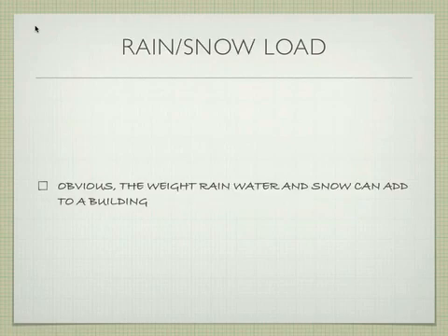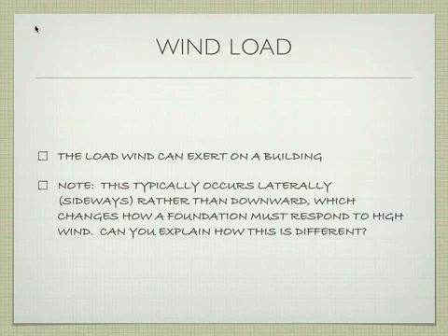How about rain and snow load? Rain, not so much. It's not that big of a deal. If you have a flat roof, you have the ability to pond usually because roofs are never perfect. So in that case, the rain load would matter. There's some weight to the water. If it's a pitched roof, not too big of a deal for rain because it's not going to be enough rain to cause too much loading. But certainly if you're up in the mountains and you get some snow, you'd have to deal with snow loading, right? Snow can be really heavy. It can sit for long periods of time and can significantly add to the weight of your building.